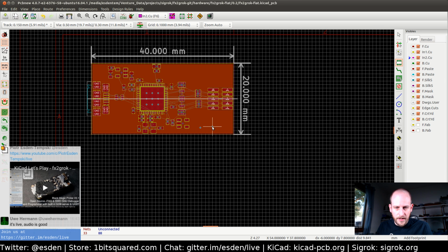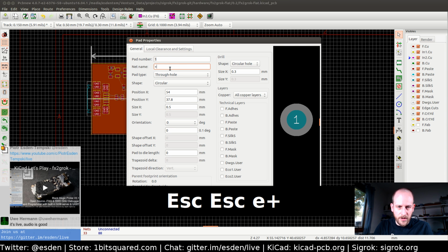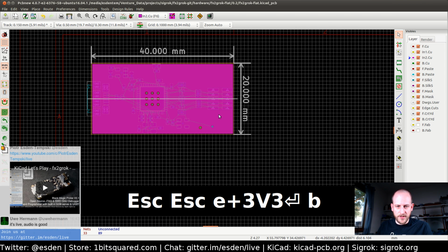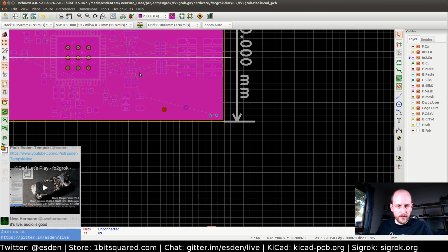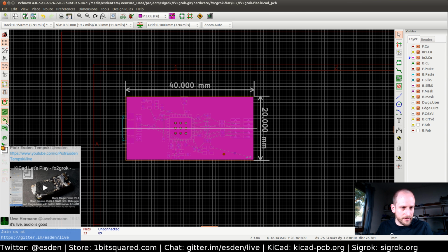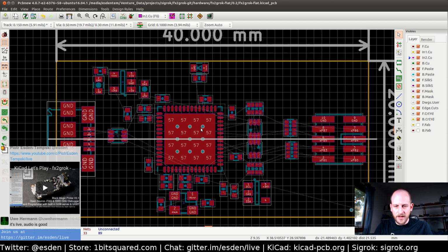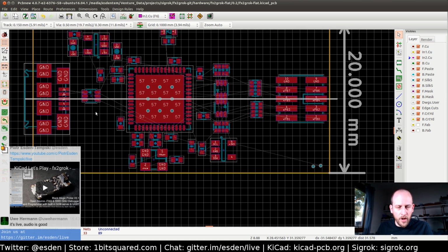Okay. But we will set the pad onto the +3V3. And now the inner one is also filled. So just temporarily we will use it later, but we have now the connection so that the fills are shown. And now on the left, do not show filled areas or zones, so we can disable it. So we have it, but we don't see it, and the rat's nest will show that it is connected there. Okay.